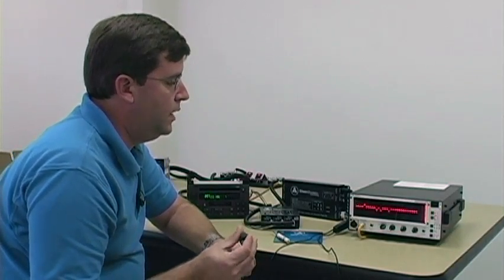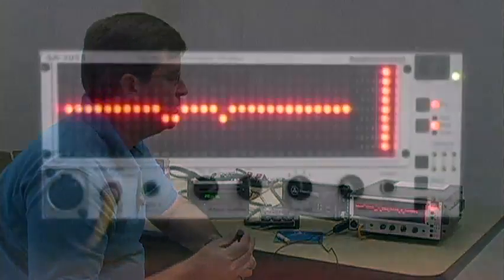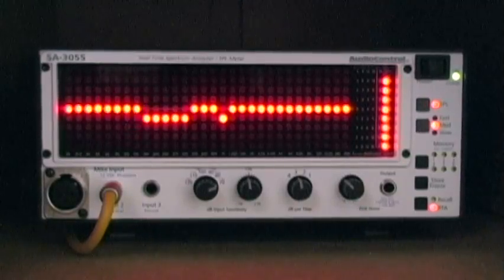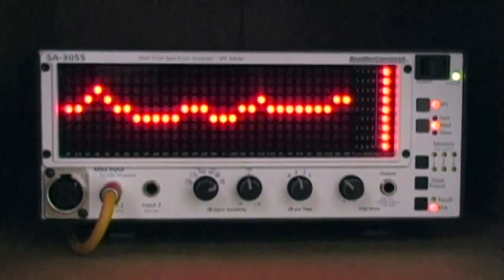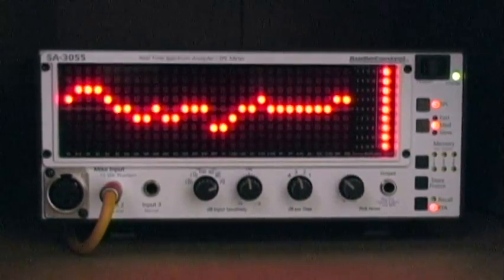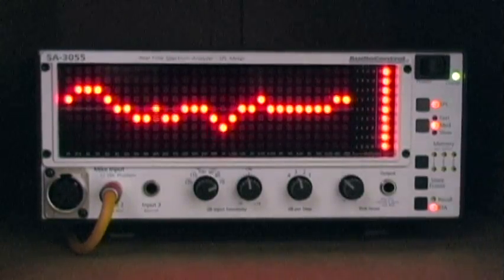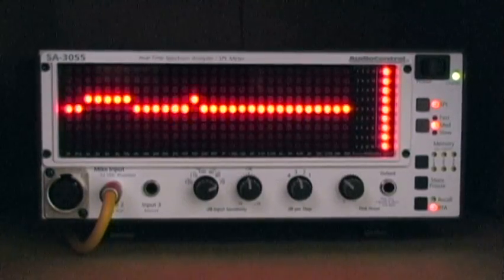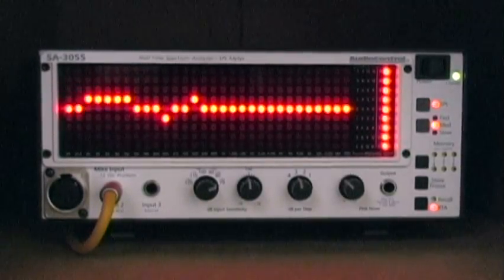And as you can see, we have a very nice flat frequency response to work with, and we're monitoring the front channel at the moment. I'll defeat the CleanSweep momentarily to show you what it started with, which is essentially the result of the summed signal between the sub and the front channel through the SSI. Now we'll go and look at the rear channel results, and we can see that we've achieved a substantially flat result on the rear channels as well. Show you what we started with there.